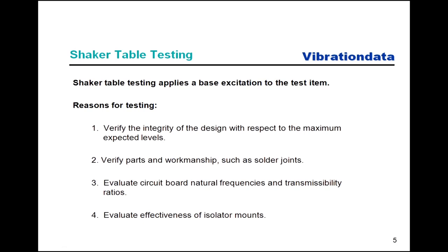And sometimes we'd even say, okay, these isolator mounts have to withstand extreme cold or hot temperatures, so we might actually mount a thermal chamber over the shaker, or mount the shaker under a thermal chamber, whichever the case might be, and would test the isolators at different temperatures to see how the natural frequency of the isolated component would change.